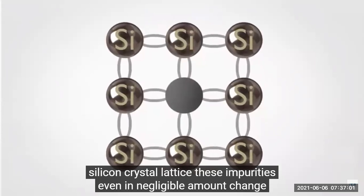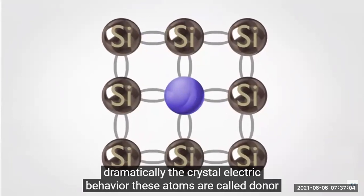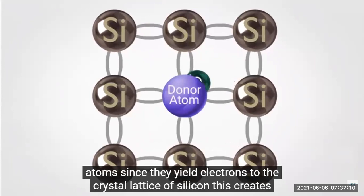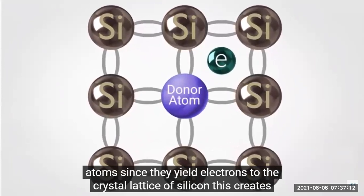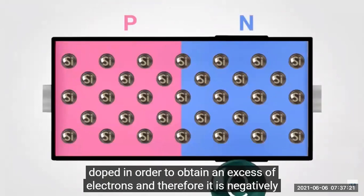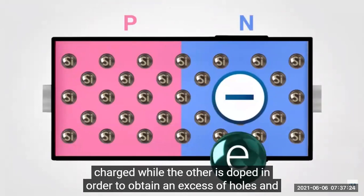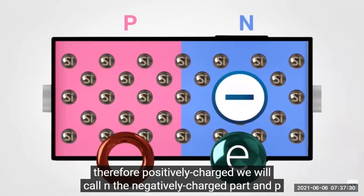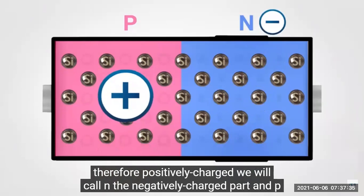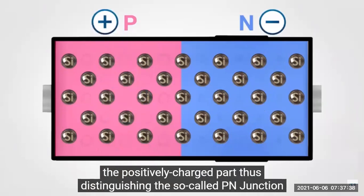These impurities, even in negligible amount, change dramatically the crystal electric behavior. These atoms are called donor atoms, since they yield electrons to the crystal lattice of silicon. This creates two distinct parts within the diode with two different charge levels. One part is doped in order to obtain an excess of electrons, and therefore it is negatively charged, while the other is doped in order to obtain an excess of holes and is therefore positively charged. We will call N the negatively charged part and P the positively charged part, thus distinguishing the so-called PN junction.